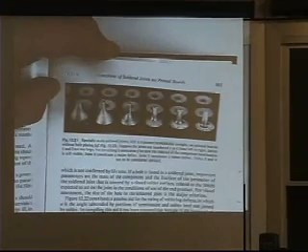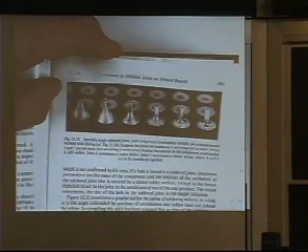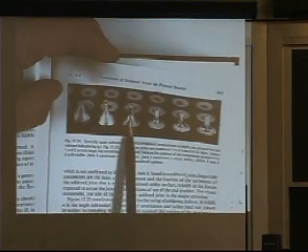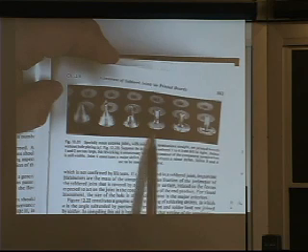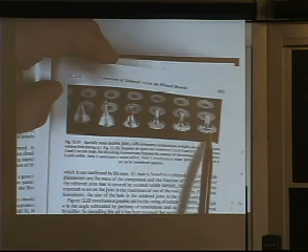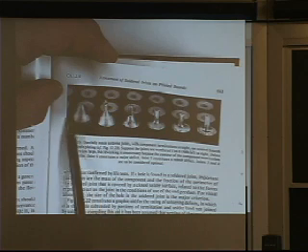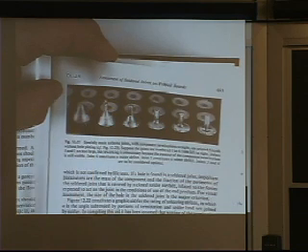This paper is very high quality. Here we have some solder balls with wires going through, and they put different amounts of solder on there. You'd like to get a nice kind of fillet that looks like this or this, a nice kind of cone. Here I don't have enough solder, but over here you actually start to see this thing start to slump. The distance across here is probably a couple of millimeters, so you're actually starting to see there is still a gravity effect.